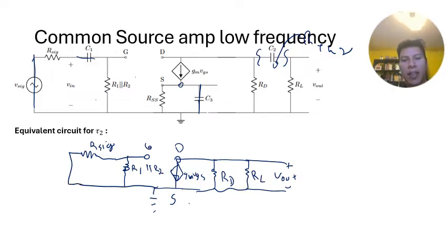Okay, so now we need to actually, oh, and remember that we needed to do R Thevenin here, so I shouldn't have drawn this line here. It should actually look like this. And then this is the R Thevenin location that we're trying to look at. In this particular case, let's do our IX VX test. So I'm going to insert my plus minus. This is IX and this is VX.